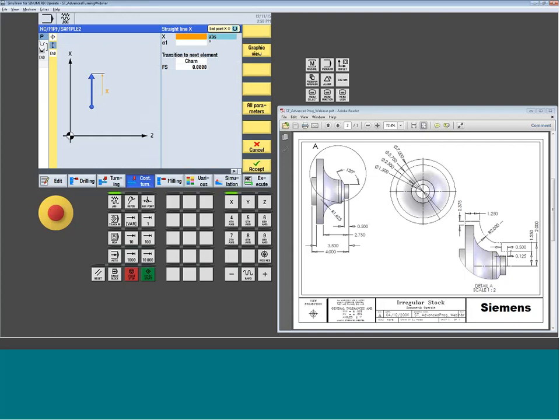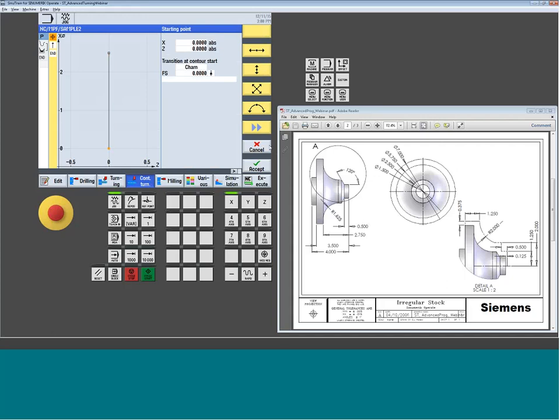Stock pulls out. So here, this is a radial dimension, so I want to make sure I go out to 2.5 because I'm telling it incremental or absolute. Or I could set this to incremental and put that value. We're going to move back in my Z. Oops, I actually did a boo-boo here because the start is not 0. The start is 1/8 out.